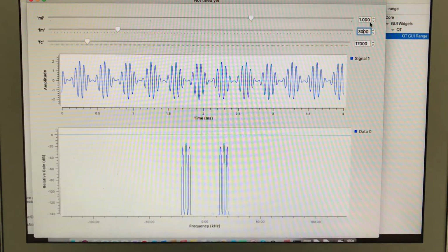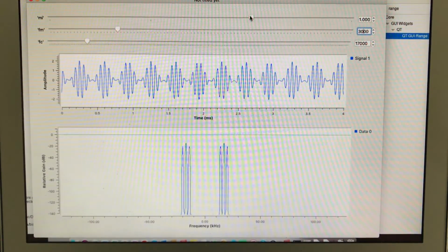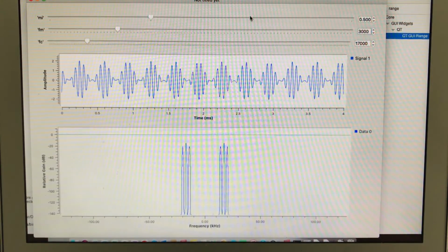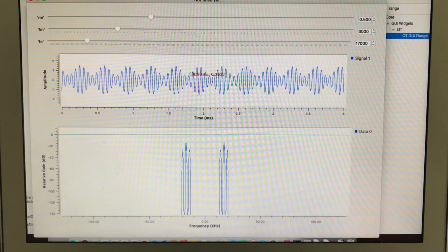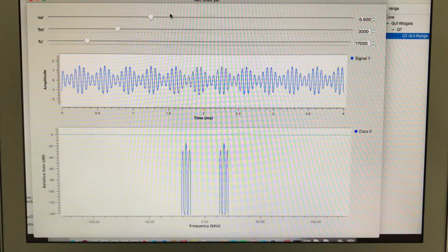Now let's try to under-modulate our system by just changing the modulation index. When I change the modulation index, as you can see, this is no more in the middle. This is no more 0. This is some value, whatever that value is, 0.5. So 1 minus 0.5, 1 plus 0.5 when you divide this. So this is at 0.5, a 50% modulated signal.